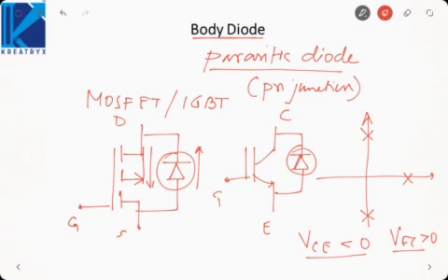So remember, whenever a diode is connected in anti-parallel to any device, the device behavior will be unipolar and bidirectional. Like if we connect a diode in anti-parallel to an SCR, by default the SCR is bipolar, but whenever a diode is connected, it will become unipolar and bidirectional. So that is the purpose of the anti-parallel diode. In these two devices, this anti-parallel diode is inbuilt, but in other devices, you have to connect an anti-parallel diode externally if you want bidirectional behavior.